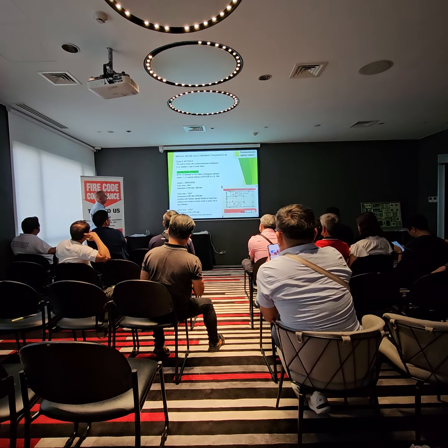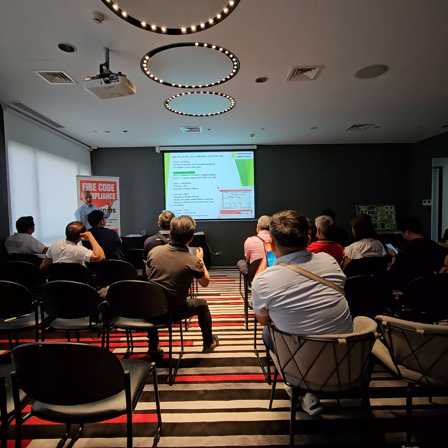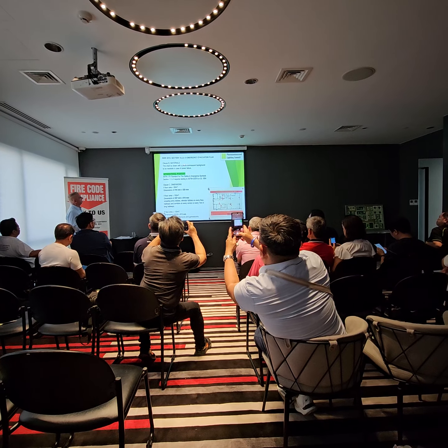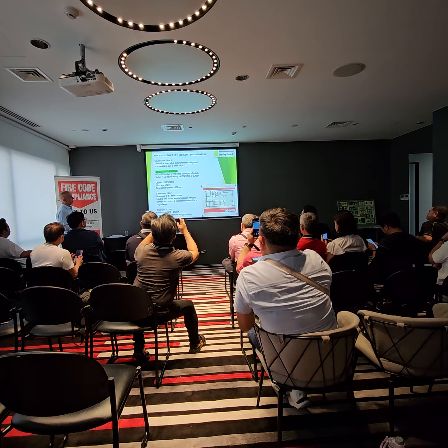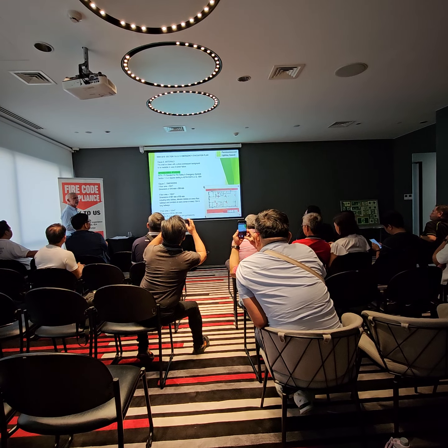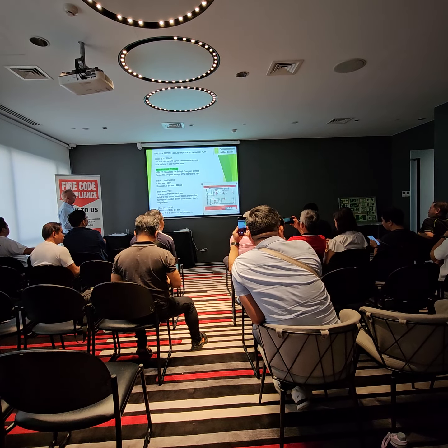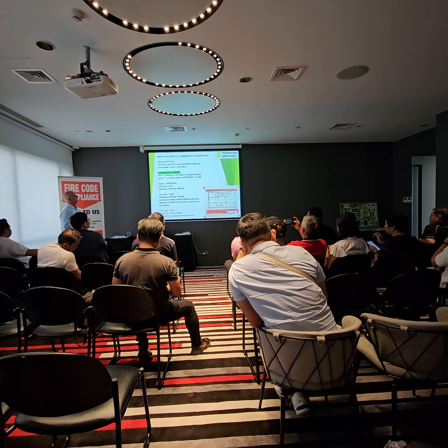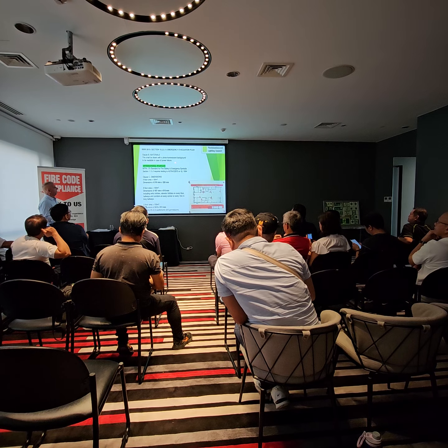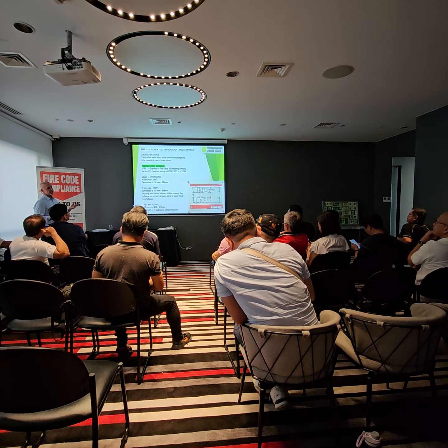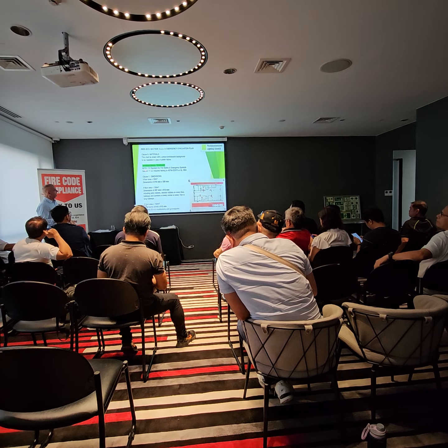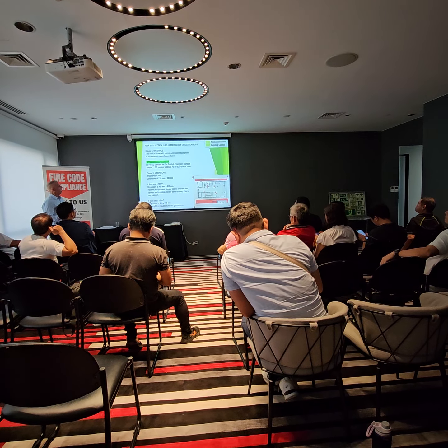Okay, so that's sort of the symbols for the evacuation plans. What about the materials? Now, this bit, I think, just appeared in the last revision. I'm not sure. Keith, were they always photoluminescent? No, only from the last revision. Okay. And the sizes as well. Oh, the sizes. The sizes and the floor area. Okay, so photoluminescent is new, but it doesn't say what standard or what brightness, but it does say that it should comply with NFPA 170.